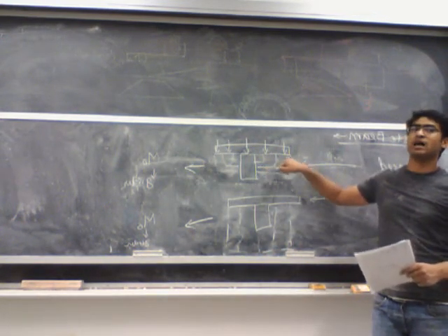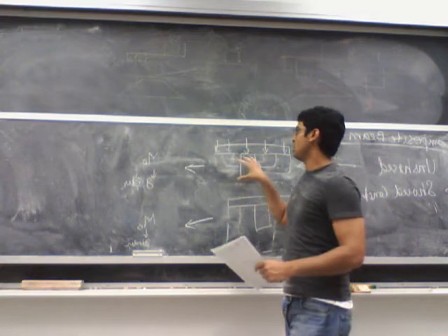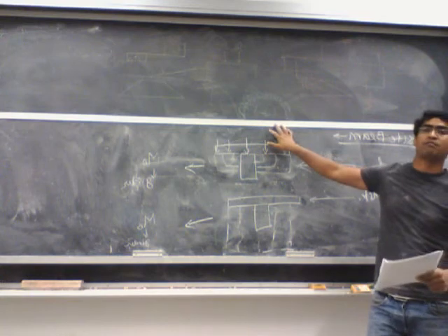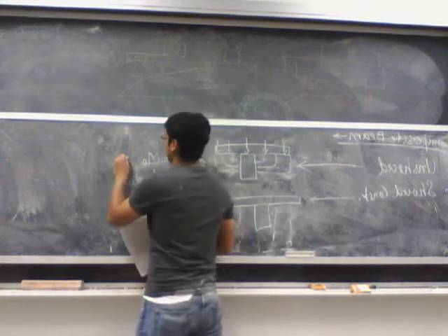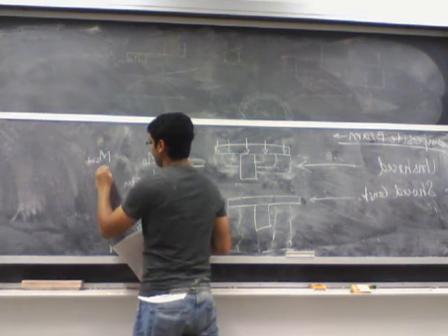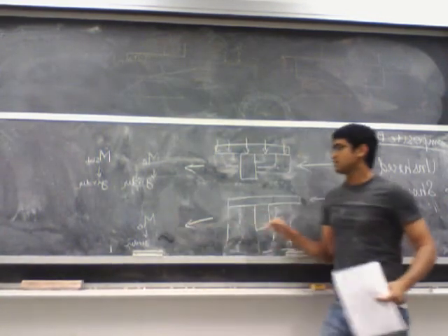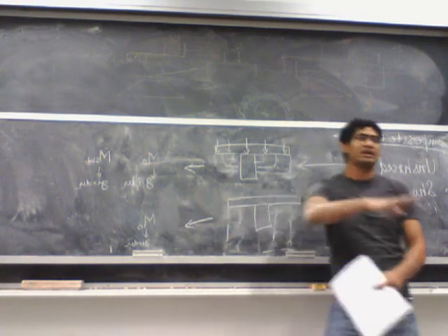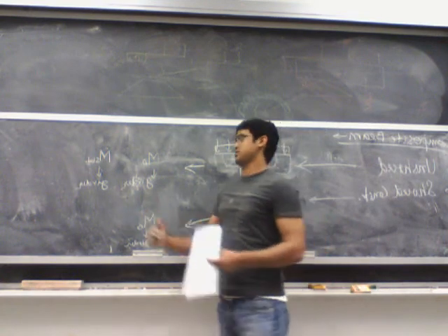For the unshored construction, when I pour the concrete for the slab, what part of the structure carries that extra weight? Since the formwork is connected to the girder, it's carried by the girder resistance. So M slab, the moment due to the weight of the slab, is again carried by the girder. In the shored construction, when I pour the concrete, it's taken by something else. I don't care what it's taken by, because if it's directly connected to the ground, it directly gets transferred to the ground.